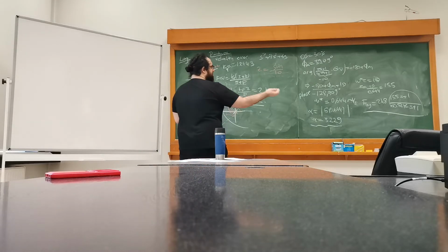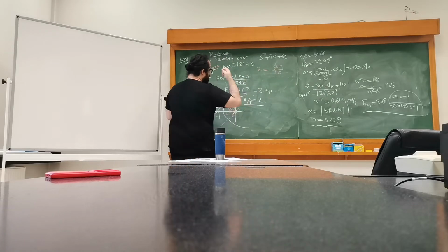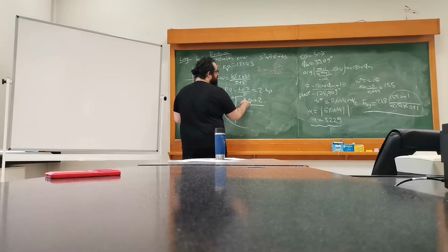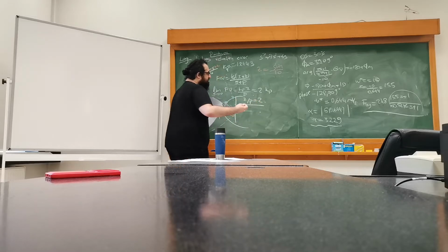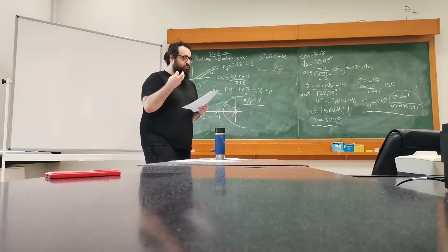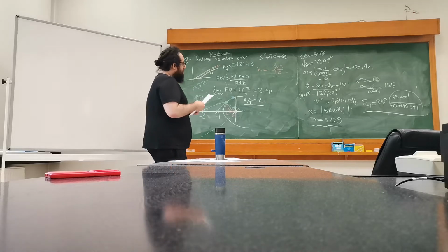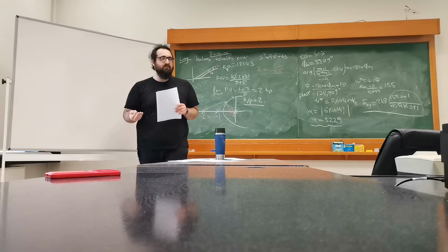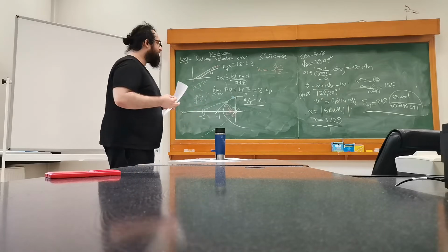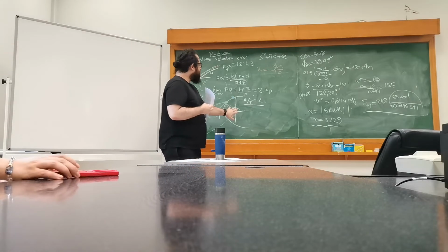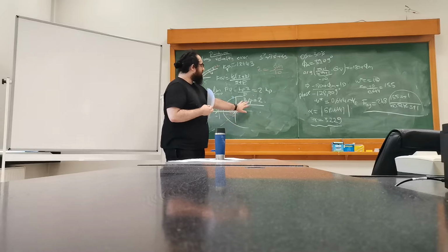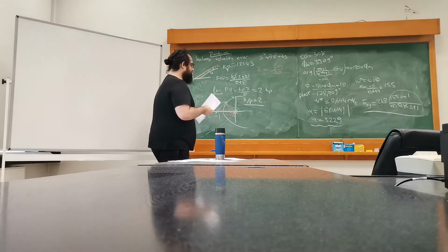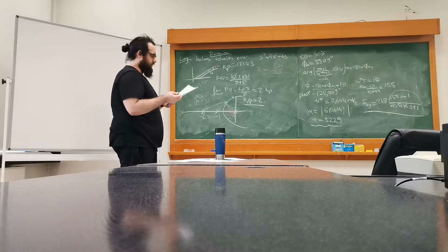And dividing that by 10, by 20, by 50, I can choose the 0. And then I can calculate where the pole should be because I have a 0 to pole ratio of 2. So they are not really that independent, but I have to choose one of them. This equation on its own shows that there are infinitely many solutions to this problem, so you can choose whatever you want. The only limitation is that the angle contribution should not be that big, and the ratio should be equal to 2. And that's it. And if the overall closed loop system is, of course, stable, you're good to go.